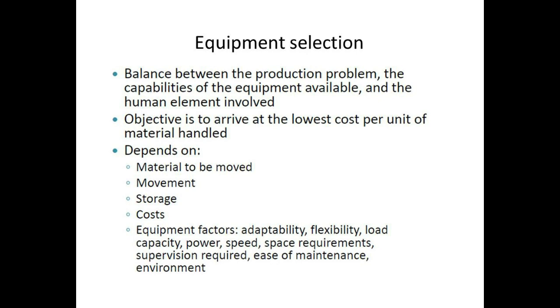Let's say the material handler is very cheap and easy to operate, but the power consumption is quite high, so it's not good for us. Then the speed, and the space requirement, that is how much working envelope it requires to handle the material. Then the supervision required.